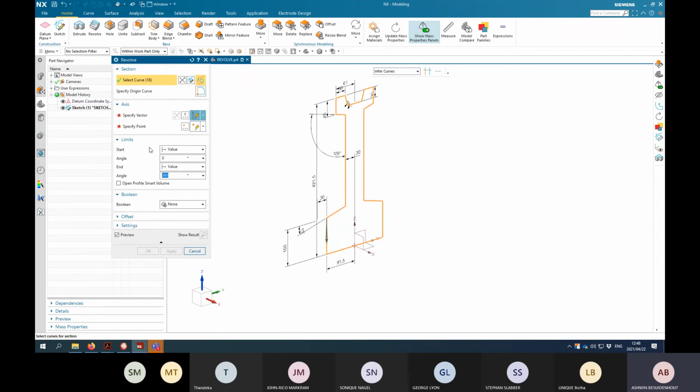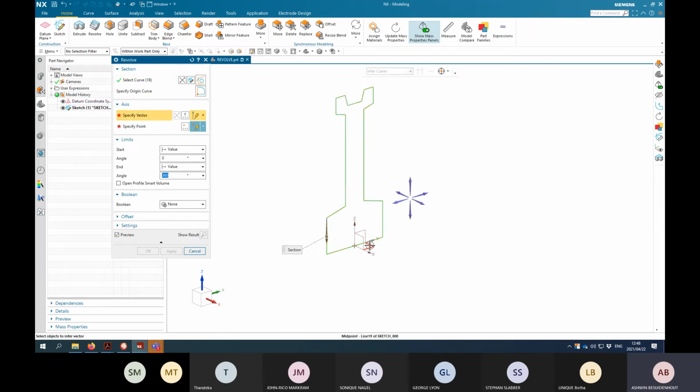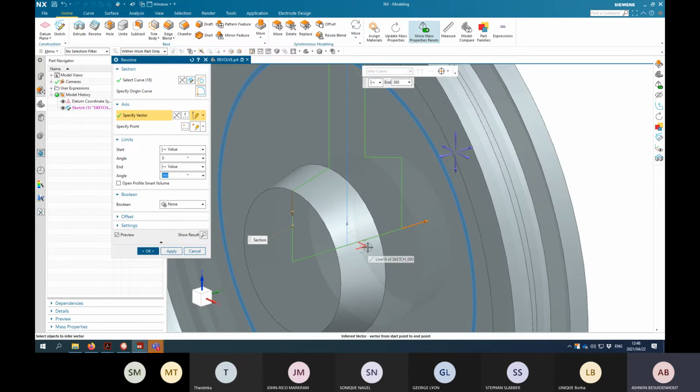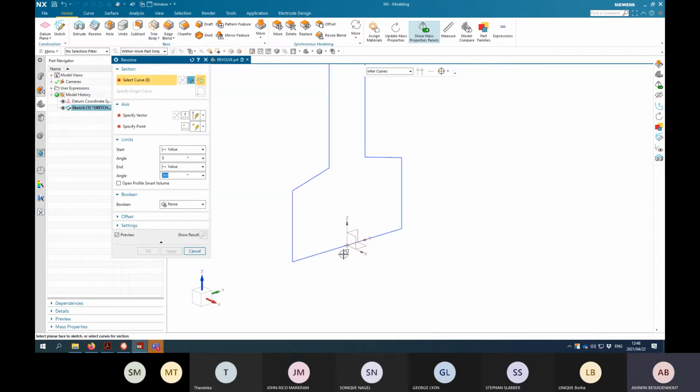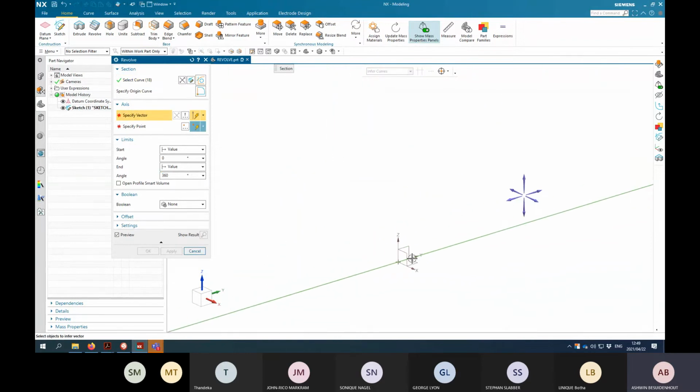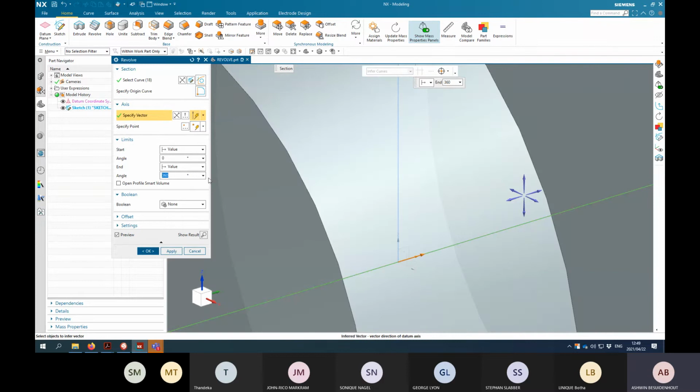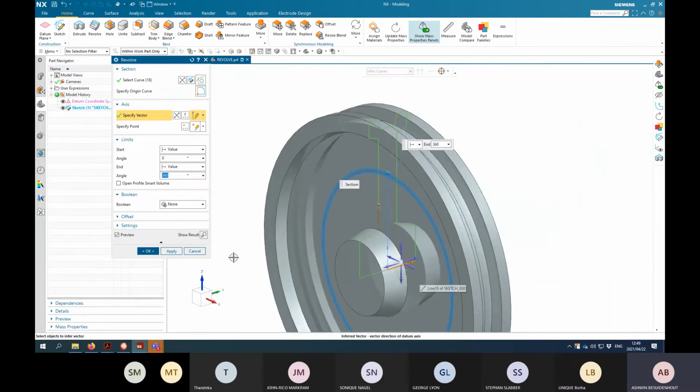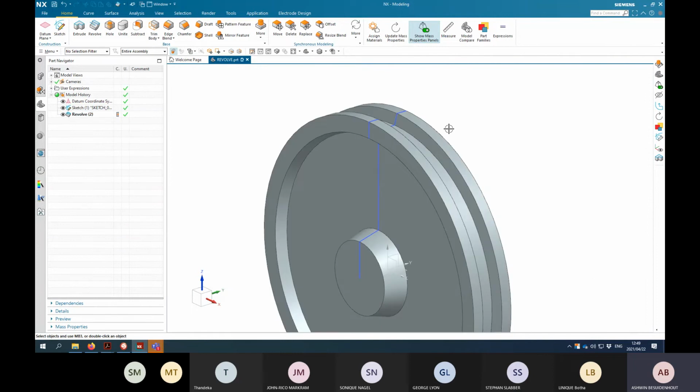Okay, so that's the thing. For the axis of rotation, you can specify this line to rotate around, but that's dangerous because if that line isn't there anymore, then the revolve will be broken. So I specifically drew it in such a way that I can make use of the datum coordinate system here, or the axis. You can just zoom in a bit, go towards that region. See, you'll get a lot of options. Click the 3 dots, then right click and select the axis from there. Then you don't need to specify any midpoints whatsoever.